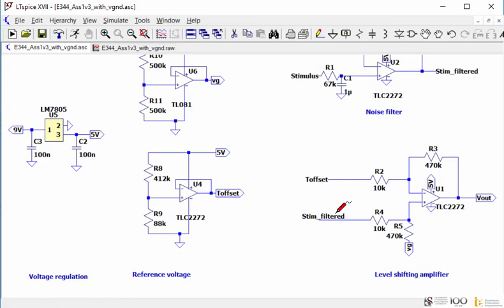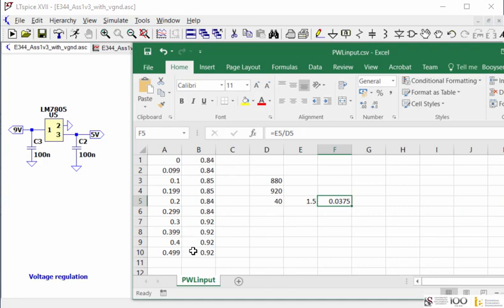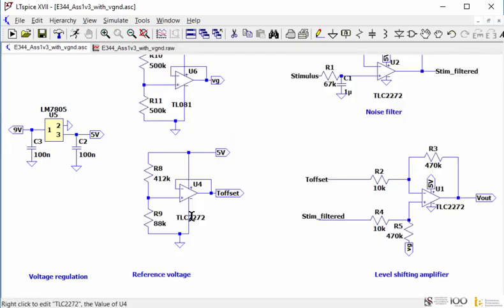Okay, so this offset I chose to be at 880 millivolts. So whatever goes on around 880, the 880 will be removed and the difference will be amplified. And that's what I want to do. So if it's perfectly 880 millivolts input, which will be 38 degrees, I want this to be 2.5 volts. If the input is 920, which will be 42 degrees, I want this to be maximum at 4 volts.